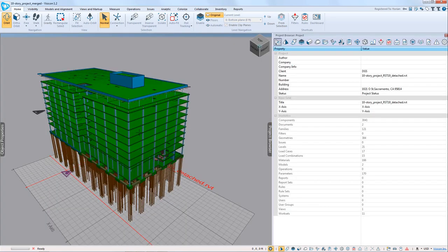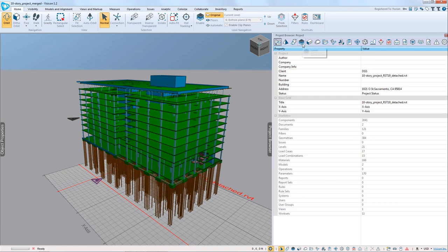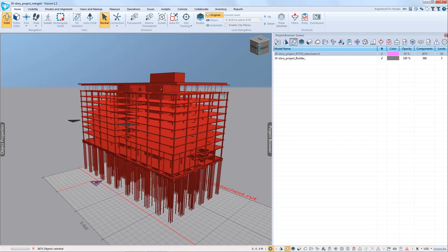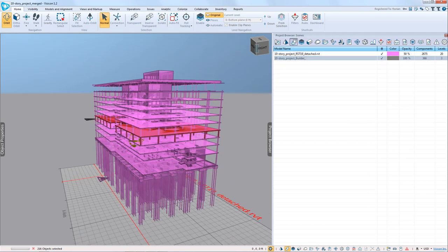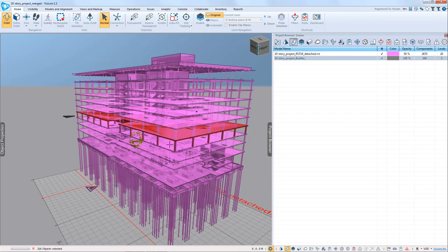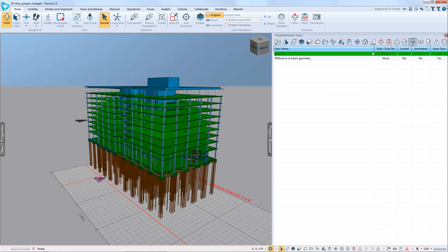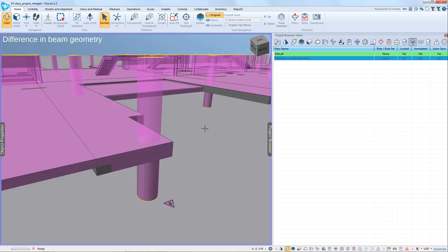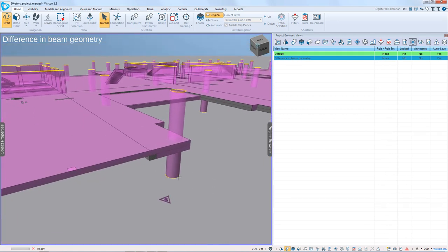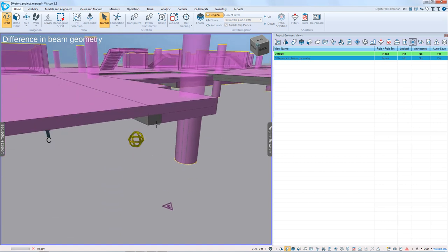On the right side, I open up the project browser, and we can see under levels, under models, this is the Revit model, and this is the adapt model. And you see I've merged in and aligned the adapt level 5 model with my Revit. I'd already gone in and created a particular view, which is isolating using the clip planes again, level 5. And I zoom in and I can see that at this location, my wide shallow beam, the gray in adapt, is actually modeled wider, so it's stiffer than what I have modeled in my Revit model.